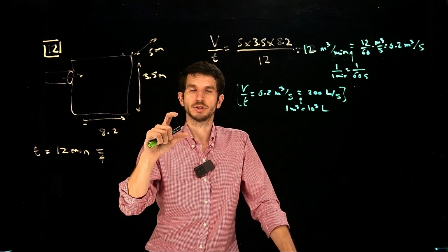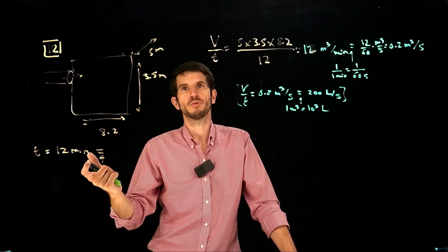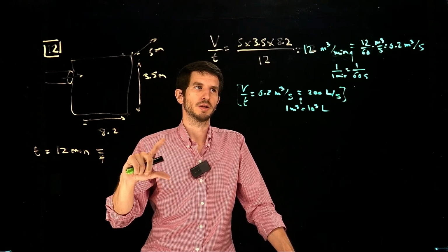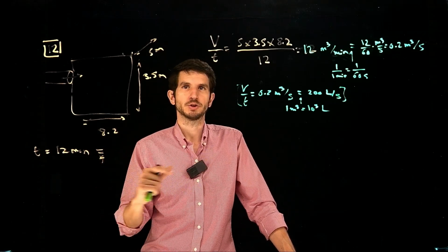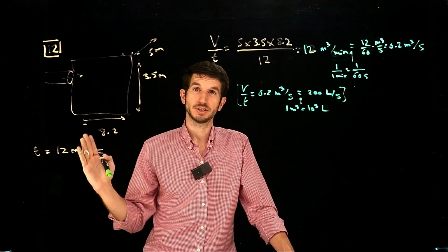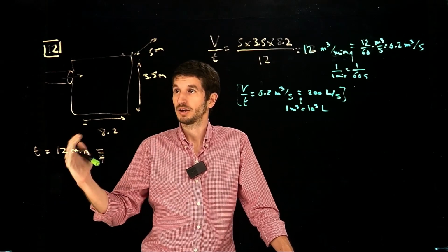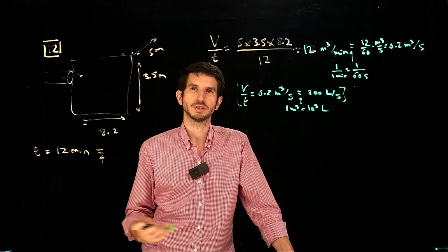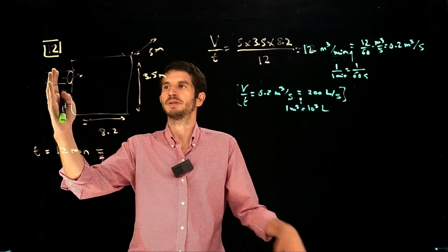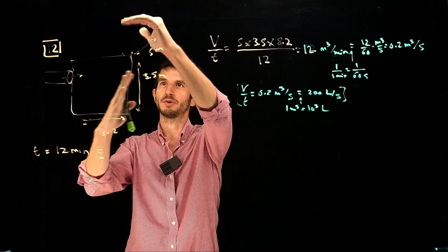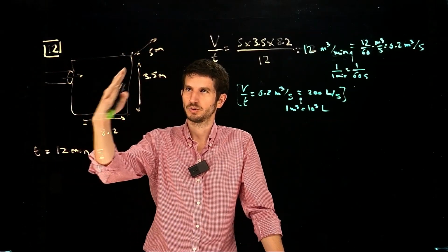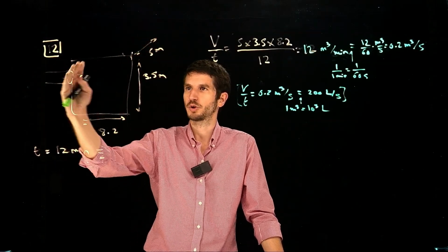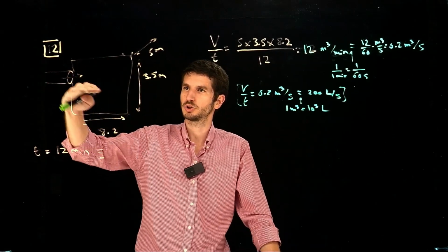And if you want to consider it in terms of cans, cans are 33 centiliters, which is about 1/3 of a liter, so that will be 3 times that. So it will be 600 cans every second of air coming in. So that's how fast this room is displacing this fluid. Why? Because every time it's pushing some fluid out, we're taking in the air just to be able to live. So there's not going to be pressurization, it's just going to flow.